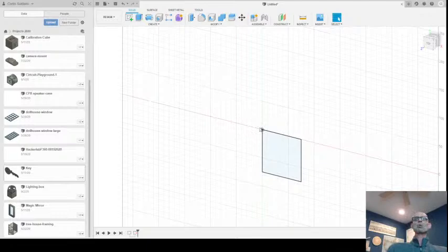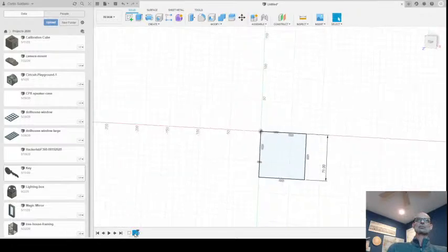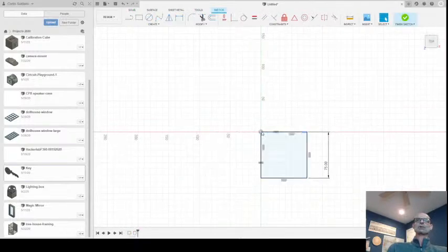All right, so that was the coincident constraint. It allowed us to set this sketch up so it's locked to the center point. It is locked to have both vertical and horizontal lines, and three of the sides have to equal this side, which is then dimensioned with a value that we've entered.